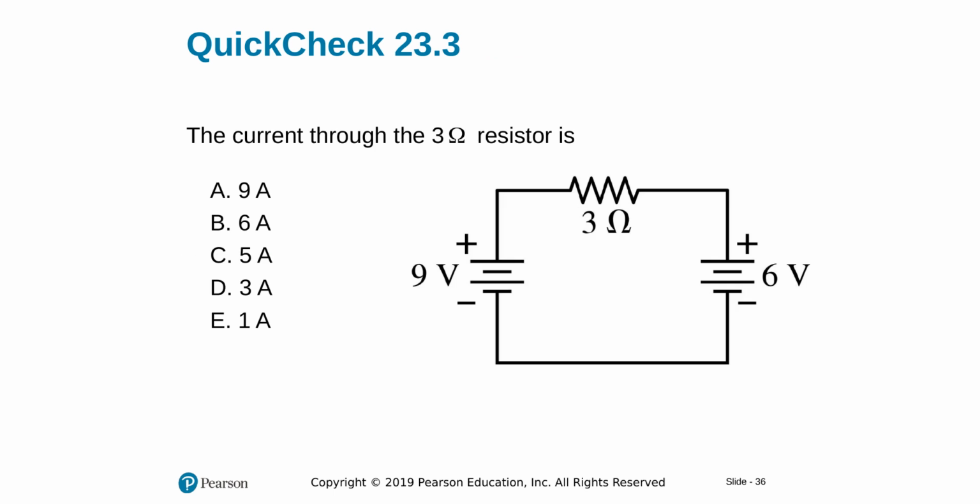The current through the 3 ohm resistor is over here. I would use the loop rule to find it. I would be going in this direction. That would be my guess, because this power source epsilon 1 is larger than epsilon 2. Minding the fact that current goes from plus to minus, this higher power direction would be enforced into the system.